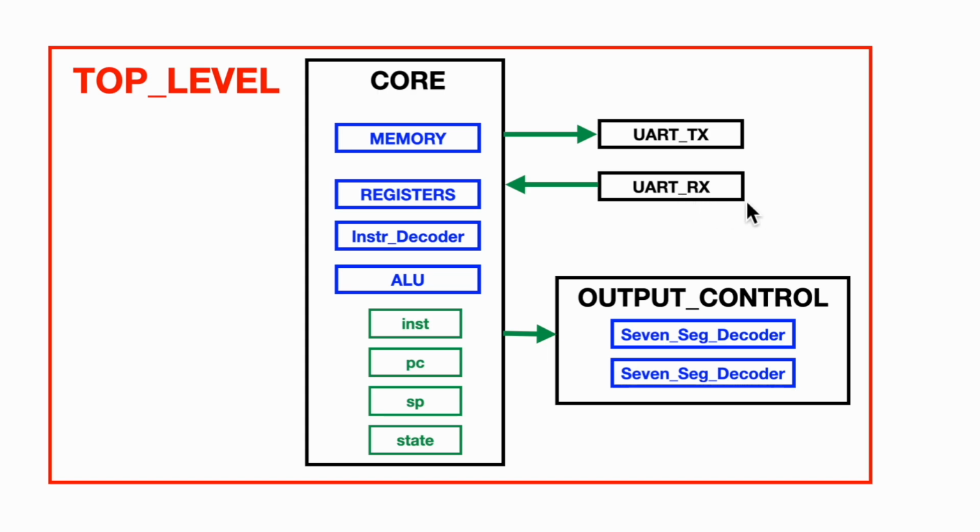In many computer systems, we can also check the status of the UART to see whether it is ready to send the next character or to see whether a character has been typed. We're not going to do that in our implementation. Instead, we will have the UART modules force the core to wait.